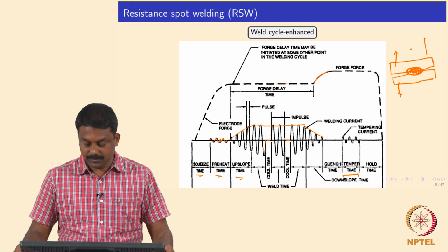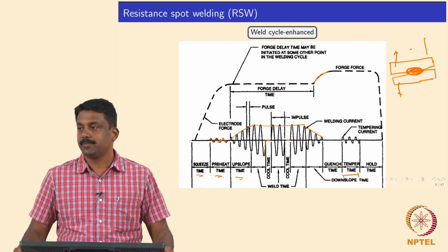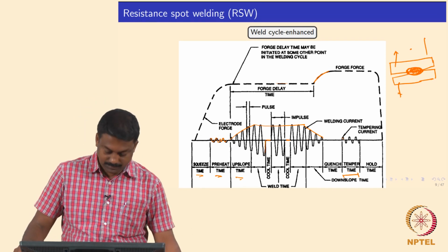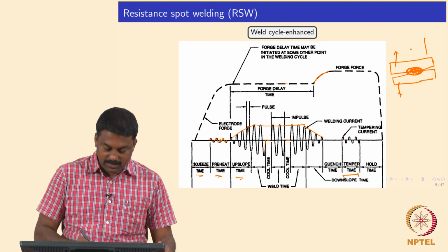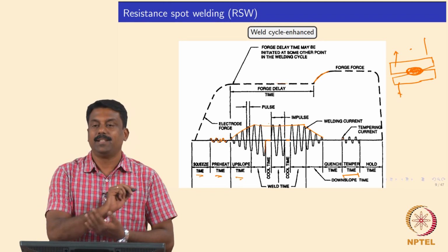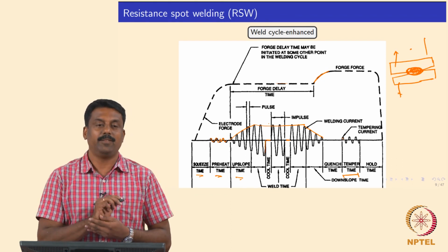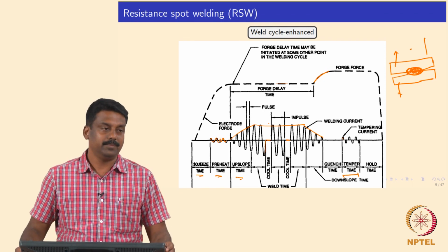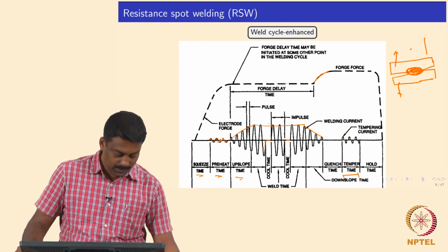Right? It's clear, the enhanced weld thermal cycle, isn't it? Good. So why is it pulsing here? Because of the alternating current. So we always use an alternating current that is preferred for resistance welding. Okay, good.